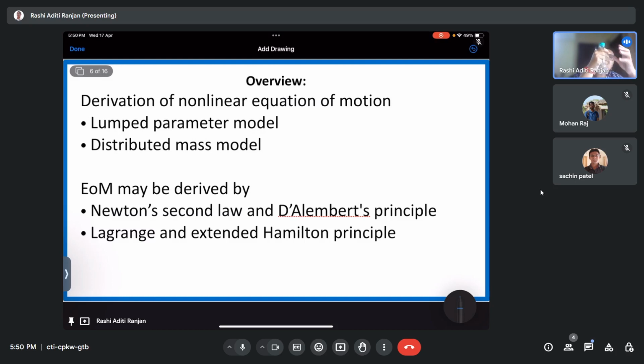Until and unless I move my hand, it is not going to perform any kind of motion on its own. However, I can apply a pressure like this on it so that it would translate. And it can also rotate like this, so 2 degrees of freedom. So what do I realize? I realize that if I constrain my system, I decrease its degrees of freedom from 6 to 2.